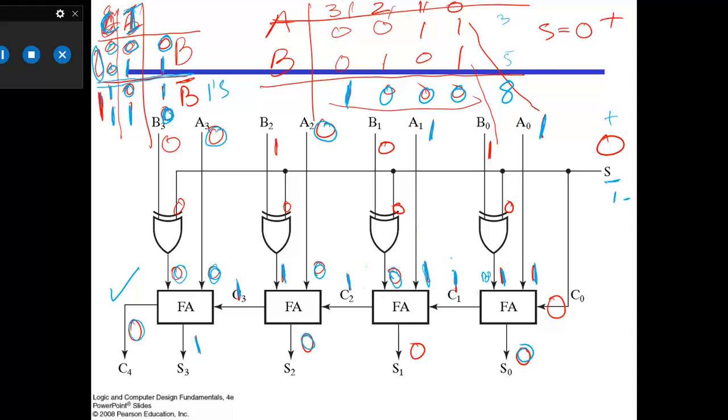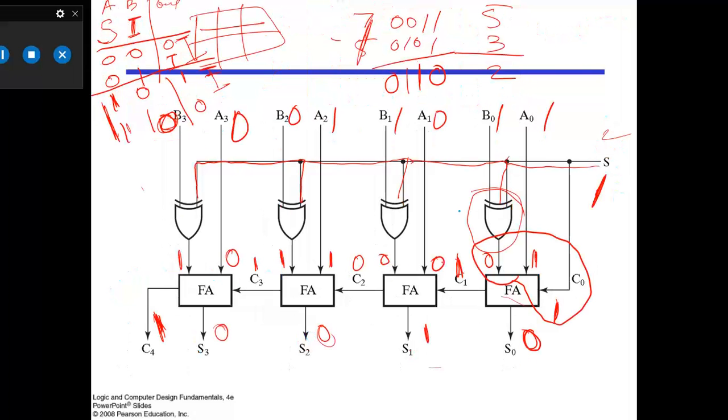This is an 8. So you need to understand this technique to understand how a full adder-subtractor works by using an XOR gate as a programmable buffer. If it was a 1 here, for the sake of argument, this 1 would have changed to 0, this 0 would have changed to 1, this 1 would have changed to 0, this 0 would have changed to 1, because 1 was here. So whatever was at the input, the complement would have been at the output, and the 1's complement result is received at the input of the full adder. And when we do the subtraction, we put a 1 here instead of a 0, so this 1 will provide the same procedure as adding a 1 to the 1's complement answer. Hence one operand is going to be the same, and the second operand is going to be the 2's complement of the number.